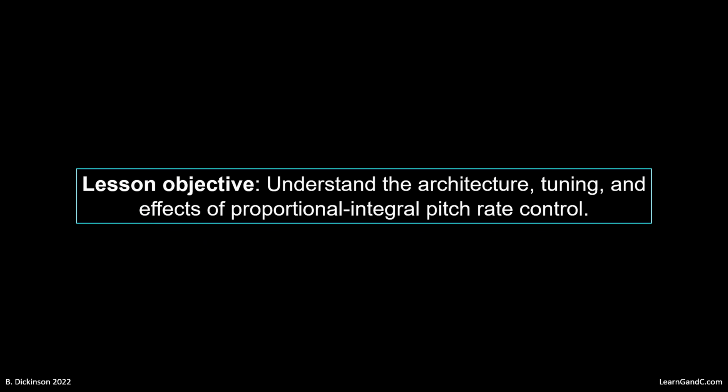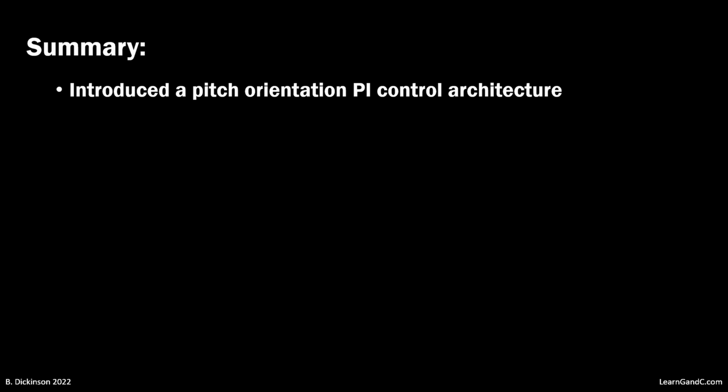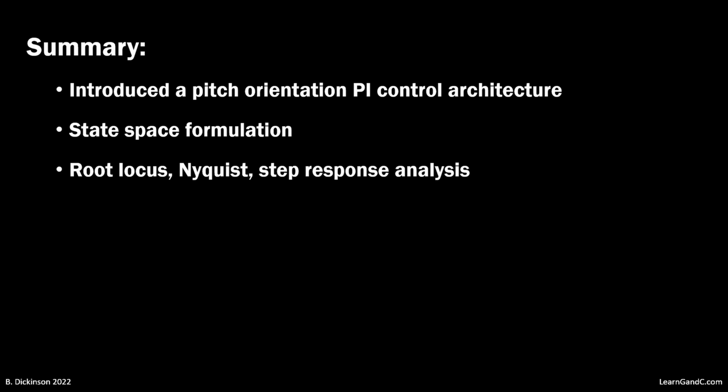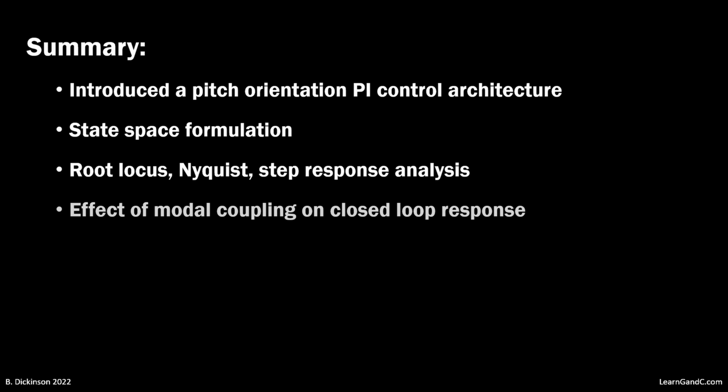Recall our learning objective was to understand the pitch rate tracking control architecture, its tuning, and its effects. Toward this, we introduced a PI pitch rate tracking controller, which only relied on pitch rate feedback. We explained the state space formulation of this controller for analysis and tuning in the time domain. We then tuned the controller with a root locus, Nyquist diagrams, and step response plots. And in doing so, we illustrated the effect of modal coupling on the closed-loop response.